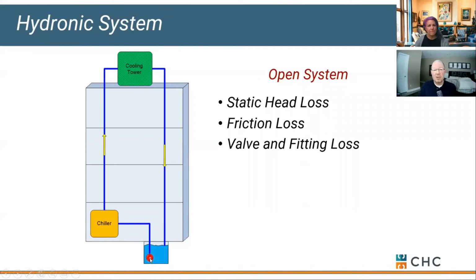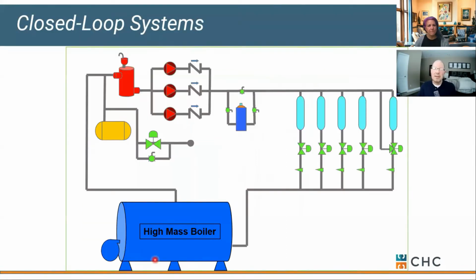So this pump is going to generate a lot more pressure than it would if it was operating in a closed loop system. The other thing with open systems, we're dealing with potential for cavitation and other pumping issues, but we'll talk about that more when we get into a pump fundamentals class, okay? But everything we're talking about this afternoon, we're going to consider a closed loop system, just to be very clear, okay? Pieces of pipe that run through our building or our campus and transfer heat.